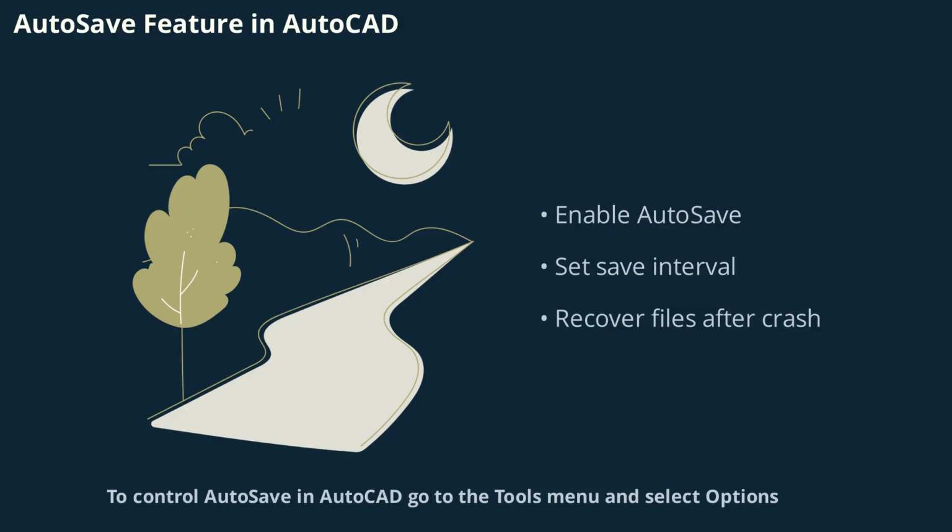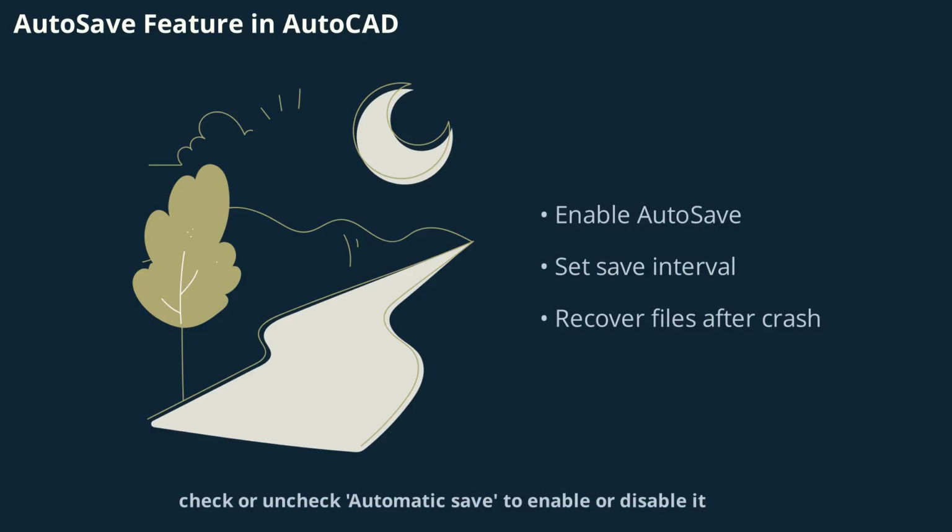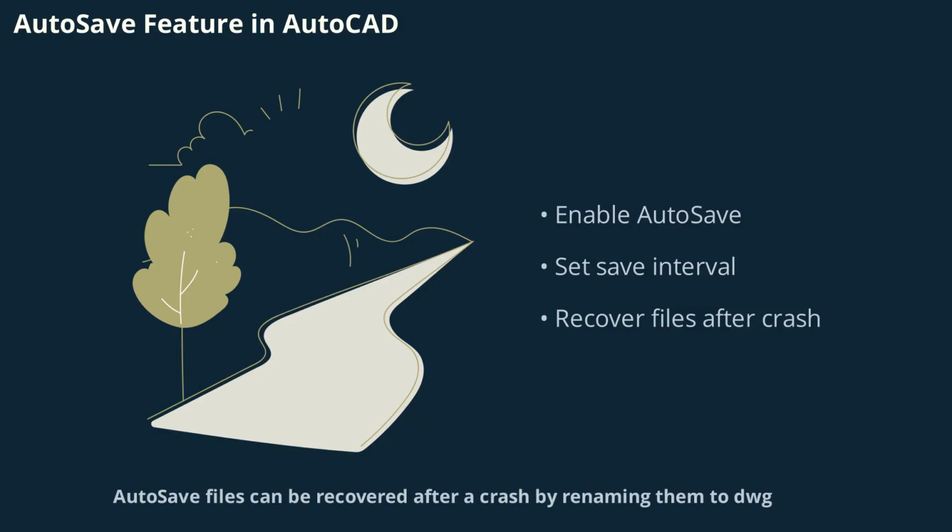To control Autosave in AutoCAD, go to the Tools menu and select Options, or type Options in the command line. In the Options dialog, click the Open and Save tab. Under File Safety Precautions, check or uncheck Automatic Save to enable or disable it. Set the minutes between saves as needed. Autosave files can be recovered after a crash by renaming them to DWG, ensuring your work is protected.